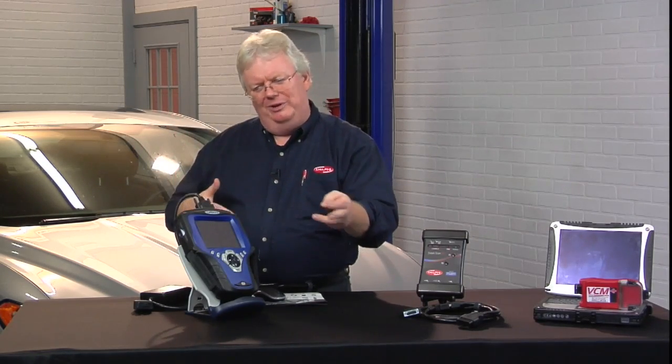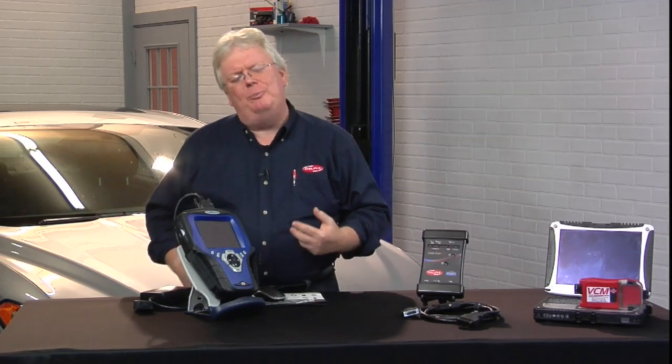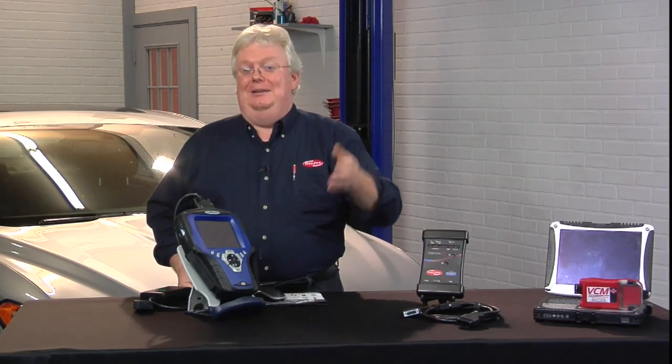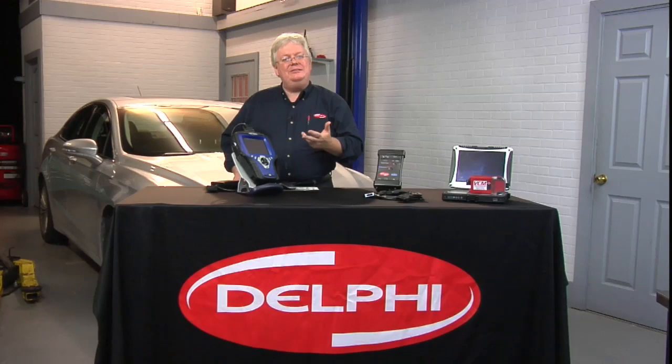It's not as much stuff as I've seen in gas engines, because you just don't have like the fuel control O2 sensors. You may have something like an O2 sensor if you have an enhanced exhaust system, the selective catalyst reduction and that sort of stuff on the 2010 and newer clean diesels. But for the most part, you will see some TIDs and SIDs, or MIDs and TIDs if it's a CAN bus diesel, EGR flow and some things like that. They will be in the mix. So Mode 6 does exist for the diesel technician, yes.